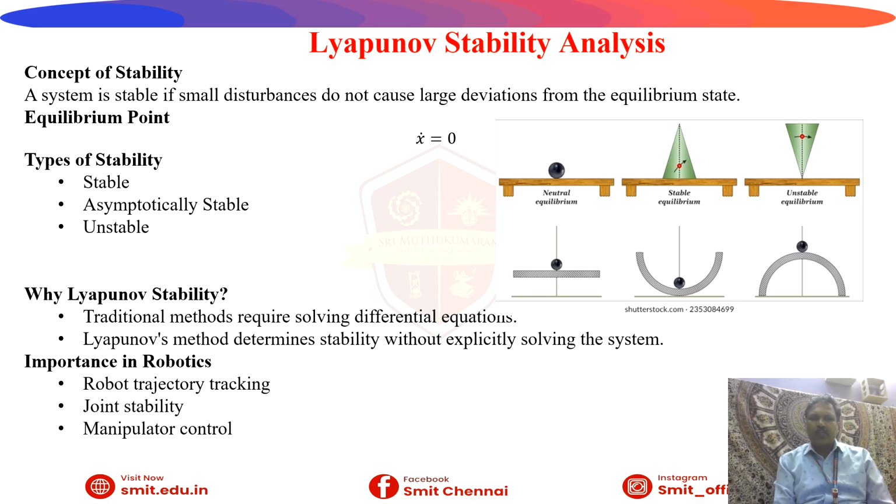Why is Lyapunov stability needed? Traditional methods require solving differential equations. The Lyapunov method determines stability without explicitly solving the system. We can see neutral equilibrium, stable equilibrium, unstable equilibrium, the various cases in the diagram. Its importance in robotics is robot trajectory tracking, joint stability, and manipulator control.